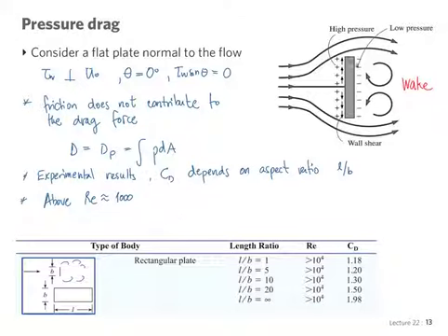The reason being that once the flow separates at this point, if this is supposed to be rather like a sharp plate, then it always separates at a specific point. And we have backflow there. It's all pressure drag, so the effect of Reynolds number is minimal.